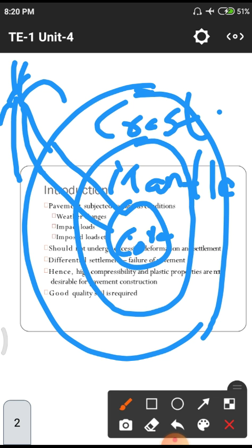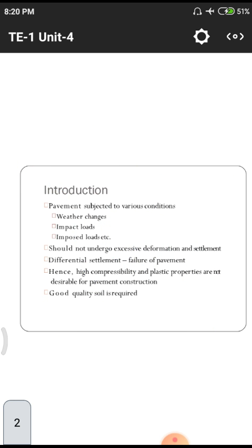Likewise, the soil strata is different in different areas, so we have to observe what area we are in and what the top layer strength is. If the top layer is very poor, automatically we have to go for strengthening by using these rollers. Those rollers will decrease the quantity of voids present in the earth surface. If we go for rolling, we simply have to go for settlement automatically. If there is any external load application, due to those load applications the total voids decrease and the total road will go for settlement.